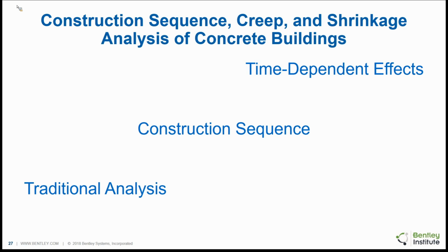Right now, the program will apply those crack factors. But the argument could be made that in these early stages, when we're looking at these effects, the cracking probably hasn't occurred because we haven't yet seen the full loading on the structure to create the cracking. And so the argument could be made that for this analysis, the factors shouldn't be applied. And I can appreciate that argument.